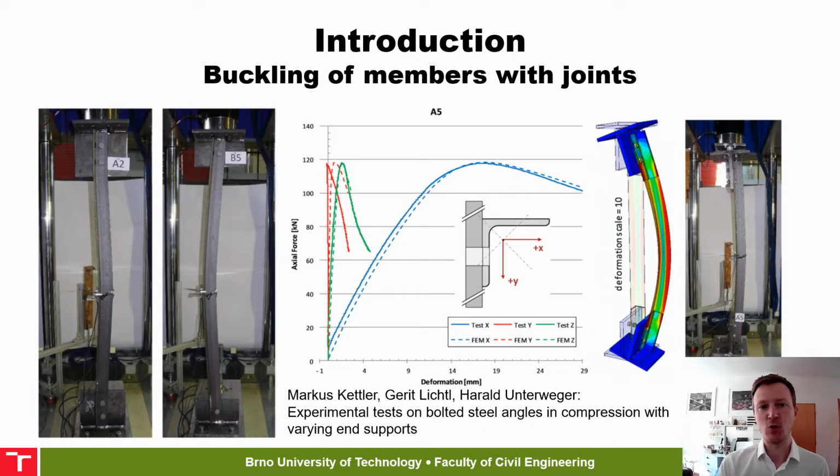One example where design of members including connections, considering their stiffness, may be beneficial is angle in a truss connected by gusset plates. We always assume that its buckling length is equal to the system length. The buckling behavior is however quite complicated. There is a shift and rotation of member axis compared to the gusset plate, and the connection has some stiffness. The design of angles, connected especially by quite stiff welded connections, bring savings.